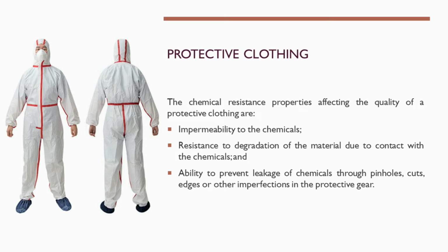Selection of suitable protective clothing against a dangerous chemical or a chemical operation depends on the risks involved and the protection required. The selected protective clothing should be made of suitable material and in an appropriate form in order to provide protection against the risks involved. For small scale use and handling of chemicals of low risk or where the risks have been controlled to a reasonably low level, protection can be achieved by clothing that prevents contamination of the body or personal clothing inside.